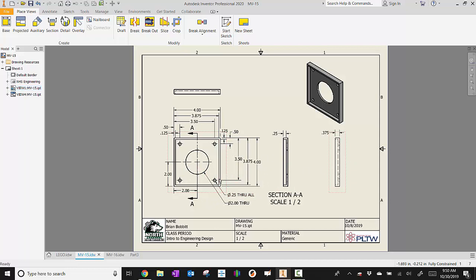And that's when I start looking at these views. This is the front view. It's not really going to tell me the depth that I need to know. So what I'm looking for is the depth from that red right there to that red, and this view doesn't show me. This view just gives me the total depth, because we couldn't dimension to a hidden line. We put a section view in, and it tells me that depth. It says from the top to right there is 0.25.